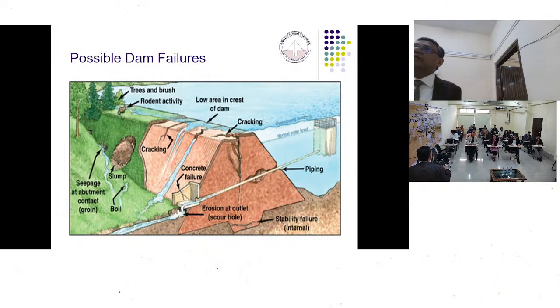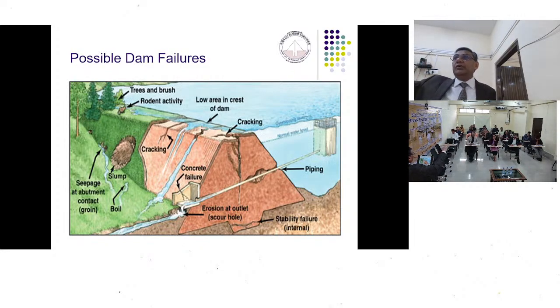Now you have to take some remedial measures. What remedial measures can you take? This is a big topic, because you may go for an additional slope, or you may try to intercept this phreatic line by some other means. You can cut it and rebuild, and lay a filter zone there, or build an additional slope over it. What I can do is cut this much portion of the dam body, lay my filter again and rebuild it, or lay a filter here and then rebuild.